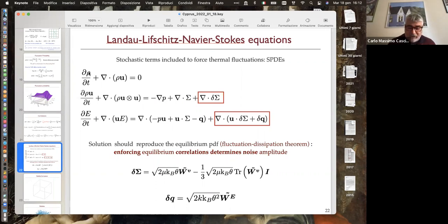When this local fluctuation of density randomly takes place on a scale which is larger than the typical nucleus of the bubble, which is set by the thermodynamic conditions, say by the local pressure and temperature, then you form a true bubble. So the bubble starts to expand and becomes a mature bubble. So it's no more reabsorbed, and it stays there. Okay, so this is the mechanism by which you form the bubble in this system.